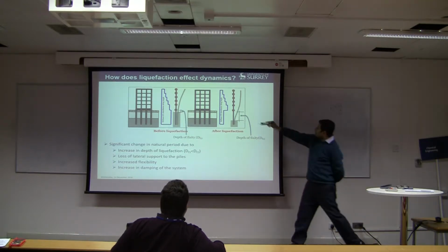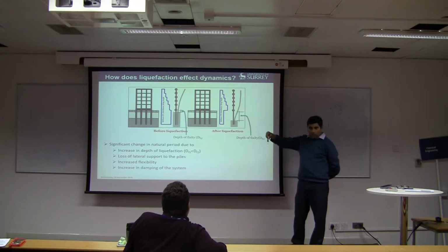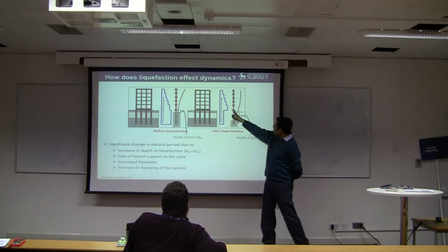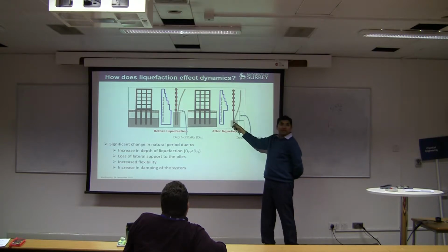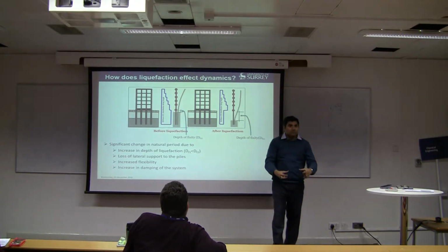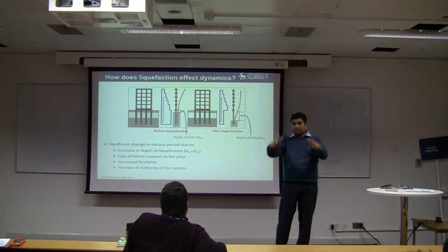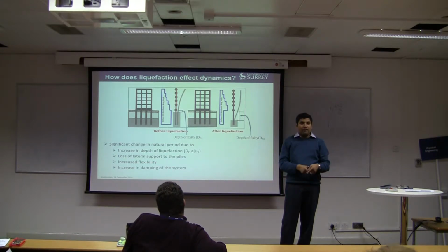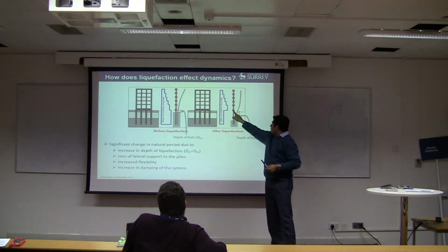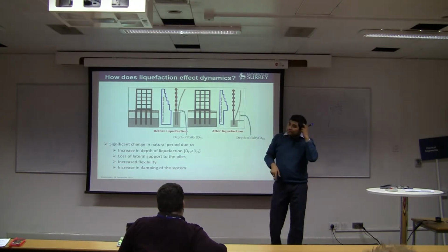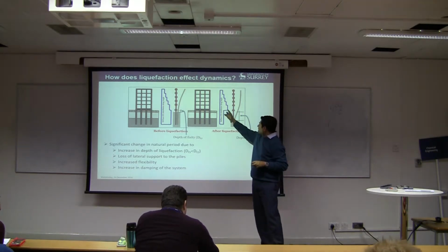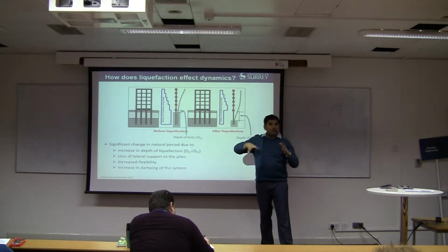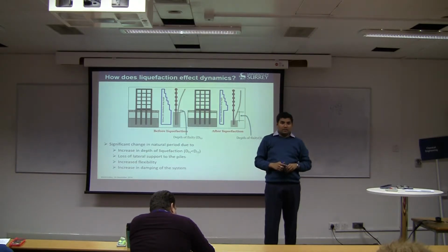So as L increases, you start to drop stiffness. That's why you see a very big drop, because L is quite large. Typically, you have a column that goes into a pile cap, and from the pile cap you get piles. So you can see there's a very big drop in stiffness, and if you have a change in stiffness, this becomes a vulnerable zone of a building.